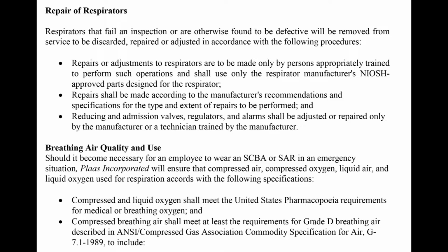Repair of respirators. Respirators that fail an inspection or are otherwise found to be defective will be removed from service to be discarded, repaired, or adjusted in accordance with the following procedures. Repairs or adjustments to respirators are to be made only by persons appropriately trained to perform such operations, and shall use only the respirator manufacturer's NIOSH approved parts designed for the respirator. Repairs shall be made according to the manufacturer's recommendations and specifications for the type and extent of repairs to be performed, and reducing and admission valves, regulators, and alarms shall be adjusted or repaired only by the manufacturer or a technician trained by the manufacturer.